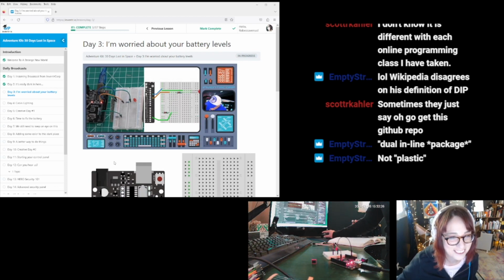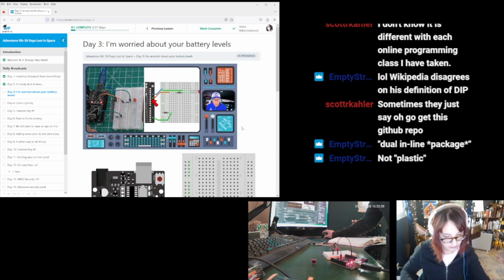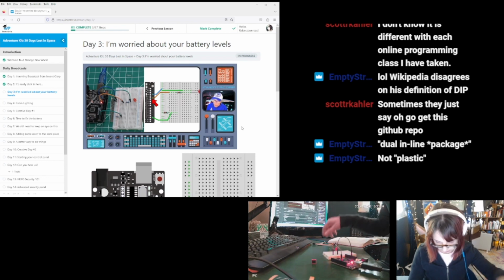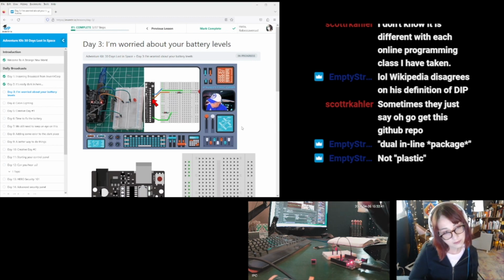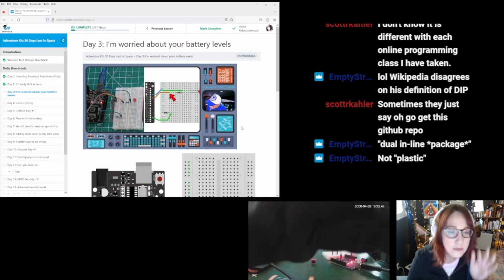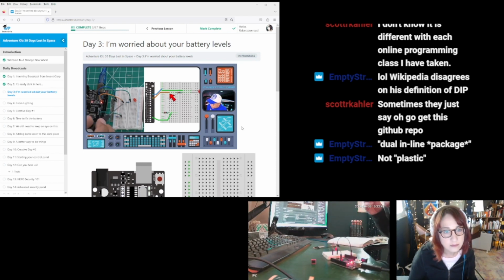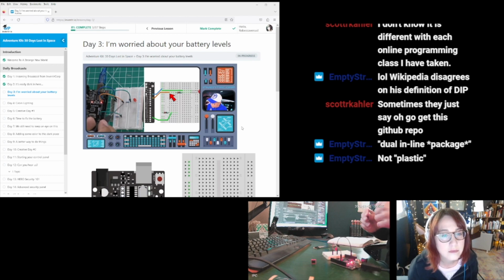A circuit that begins on pin 12, and you remember that last time we were able to ask the Hero to connect pin 12 to 5 volts when commanded. And so from that, we connect to a row on the breadboard. In this case, it happens to be also row 12. Wouldn't have had to be row 12, though. It could be any place we conveniently wanted to build the circuit.